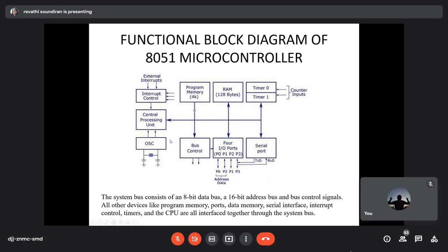You have seen in the microprocessor itself the timing diagram. It is based upon the clock cycle only that your instructions are executed. You have something like crystal 1 and 2, provided for connecting a resonant network to form an oscillator. A quartz crystal is used for the purpose of the oscillator, and this crystal frequency is going to be the basic internal clock frequency of the entire microcontroller unit. All the internal operations are synchronized with respect to this frequency.